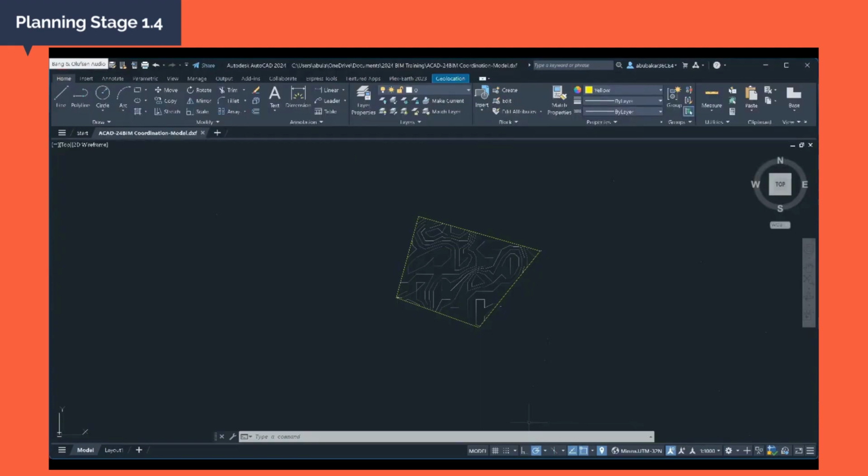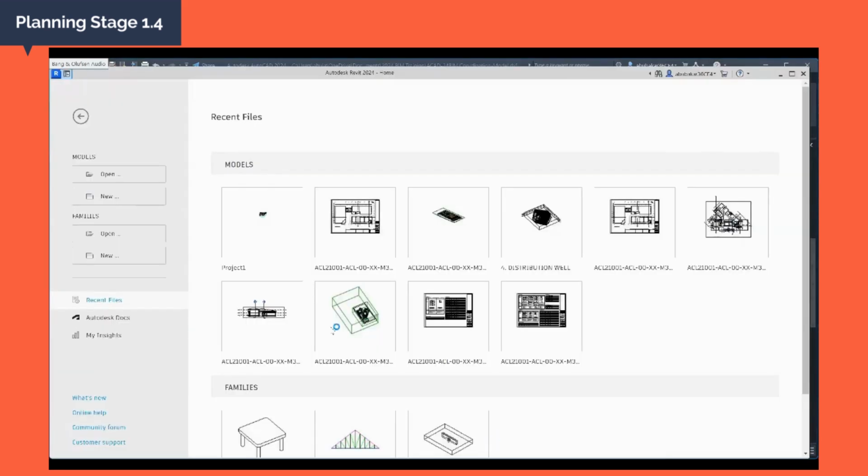The thing you do when you want to set up a project in Revit is to coordinate the site from Civil 3D and update the base reference for all your other vertical BIM applications. So let's see that. Now we assume that we're creating a new file here, new. If you already have a project that you have done in Revit, you can open it as a Revit project template.